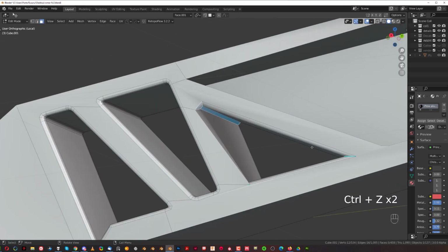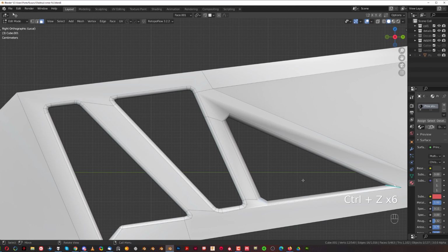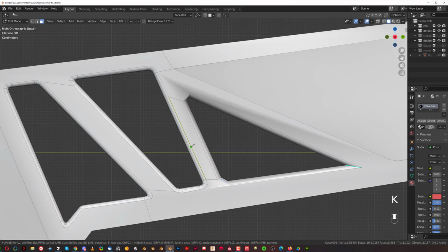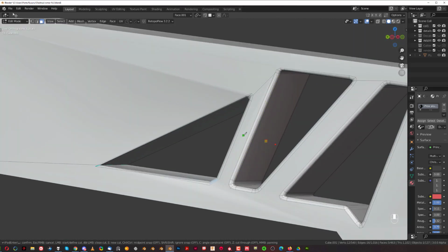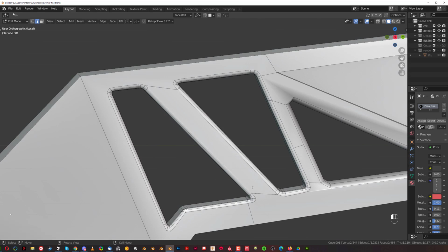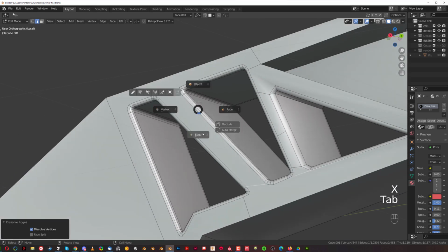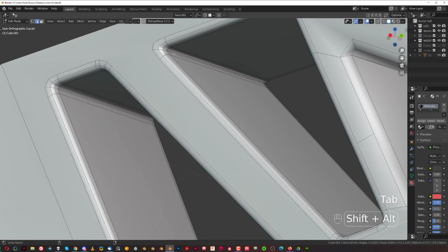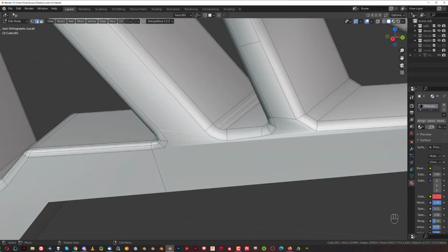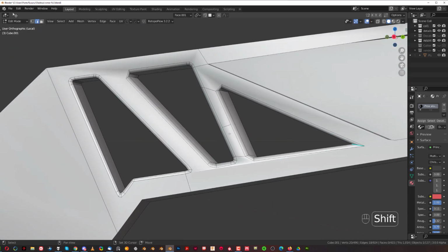Alright. Probably before we do that, I think it's not advisable to have these things go into corners. So let's just do something like this and press E, rotate it, and enter, and just remove these connecting edges, right? So okay, and then let's try again. So this one and dissolve, and these two, and dissolve, and these two, and dissolve,